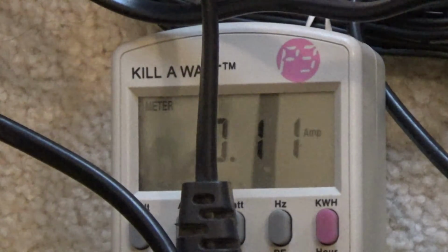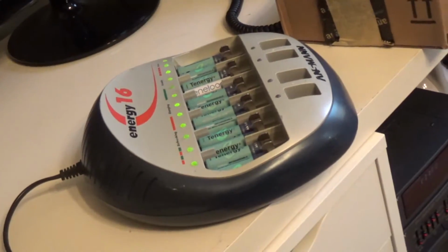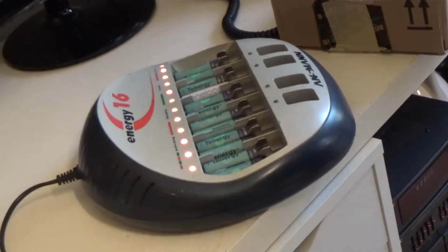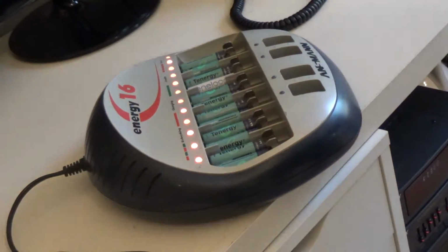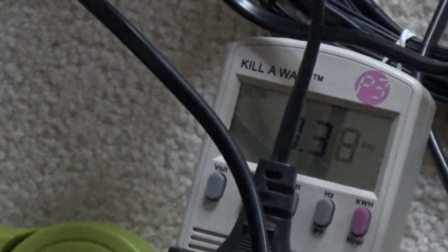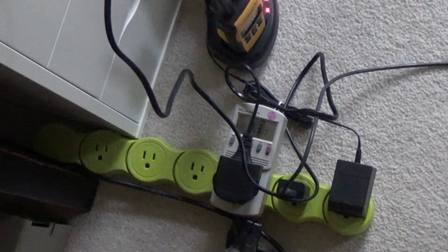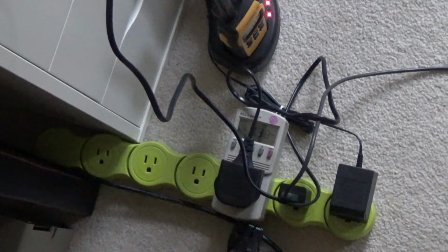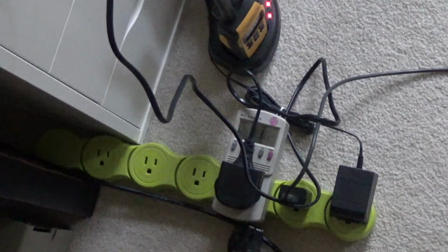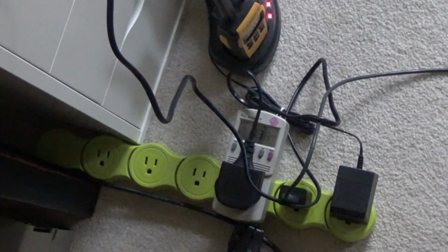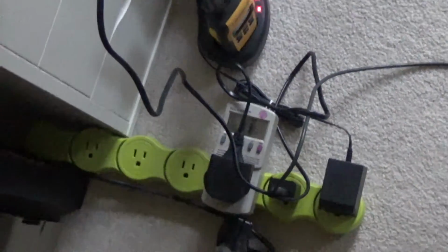We're going to have to come back in a moment when it's done with the refreshing cycle and it just goes to straight charge. I suspect it'll take a lot more power when it's just doing a straight charge. It's in charging mode now and it's drawing about 0.4. It was up toward about 0.5 a few minutes ago. Of course it's going to go down as the batteries become more full. So I think what I will do is I'm going to allot 0.5 amps for each of the battery chargers.